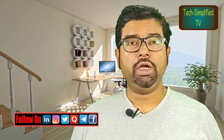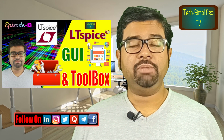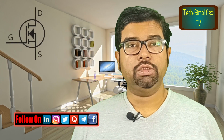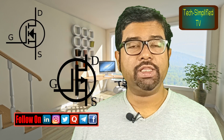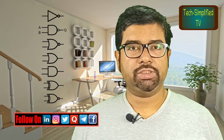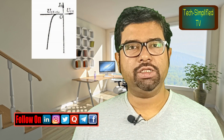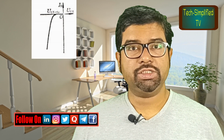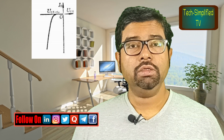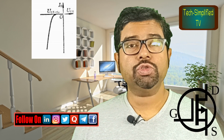Hi folks, you are already familiar with the LTSpice GUI and toolbox. In the last couple of episodes, we have used the NMOS and pMOS together as CMOS for digital electronics applications. In today's episode, we will explore the transfer characteristics, that is ID versus VGS curves, using the same monolithic pMOSFET that we have used earlier.